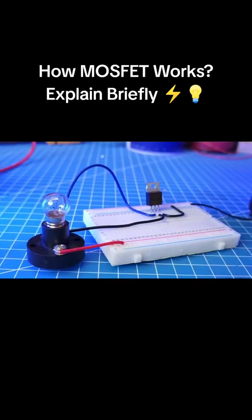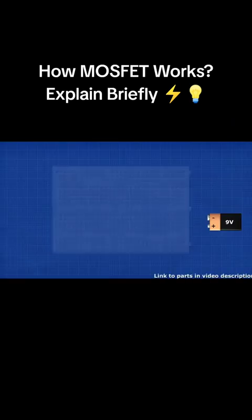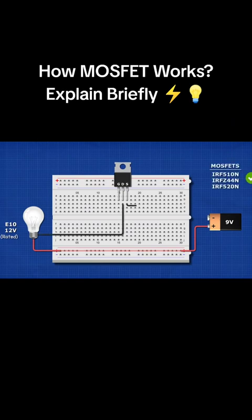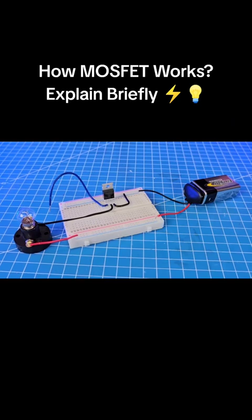Try and build this circuit yourself. Take a 9-volt battery and connect it to one side of a lamp. Connect the other side to the drain pin of the Mosfet. Then connect the source to ground. Take another wire and connect this to the gate pin. Your circuit should look something like this.